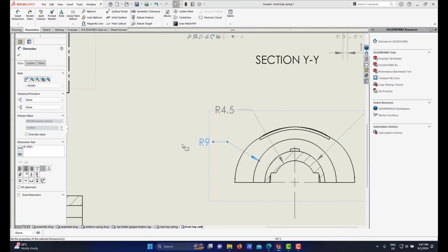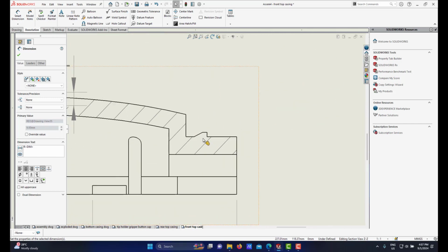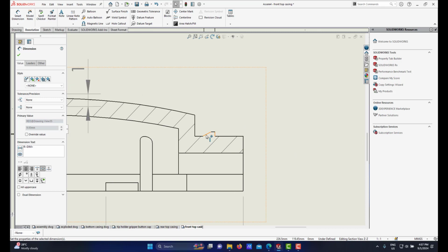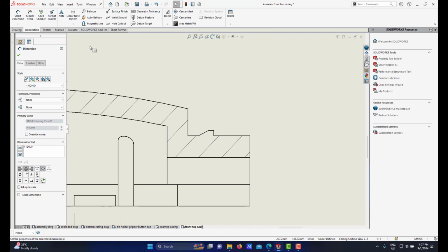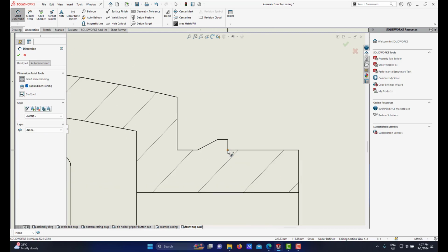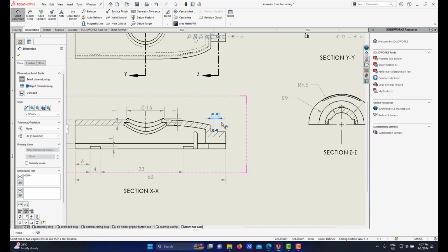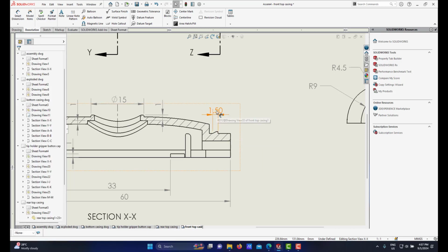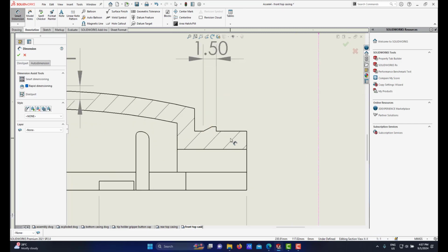All right. Okay, I think another thing I forgot to put dimensions about. We have a key feature here. Because of the cap, we have a groove or slot. So here we have a key, like snapping the cap when we snap lock into position. So I think I have to give a dimension. Show at least the length of the key like this, and also, okay, this needs to be in line like this, and I can give a dimension.